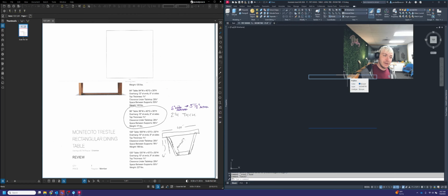So I can now delete that 30-inch line because right now this floor line is 30 inches from the top of that table. All right, so we have some other base dimensions we need to include. We've got this leg starting 6 inches in from the side, and we're going to do the same thing over here, 6 inches in, draw a line straight down, and then delete these little extra lines. So that leg has to start right there and right there.